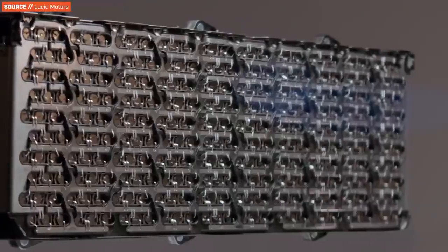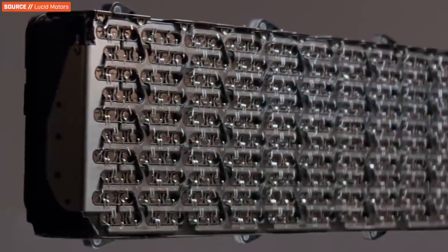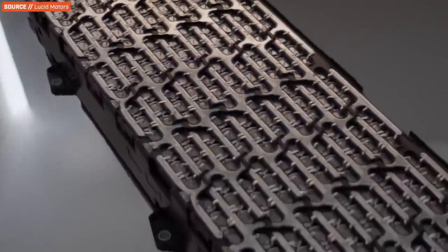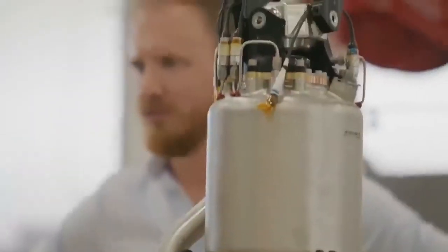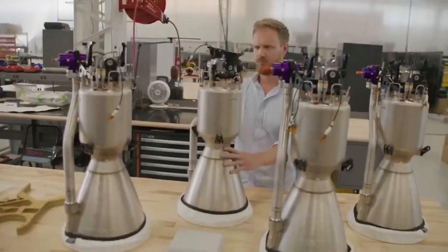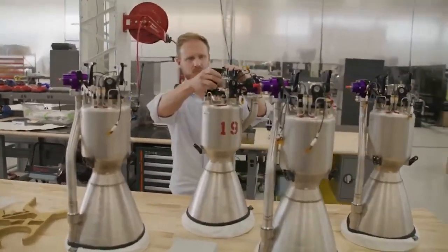So yeah, just the motors alone to power the pumps would be about 2.5 times heavier than an entire RD-170. That's not including the weight of the batteries, which don't get lighter as they drain their charge. So we'd need several additional tons of batteries in order to power this. And that's not even taking into account the power density of batteries, which is 50 to 100 times less power dense than RP-1. So even if you optimized a motor and batteries to be substantially lighter, maybe even half the weight of those on a high-performance electric vehicle, we're still looking at something a lot heavier and less power dense than a turbine and propellant.